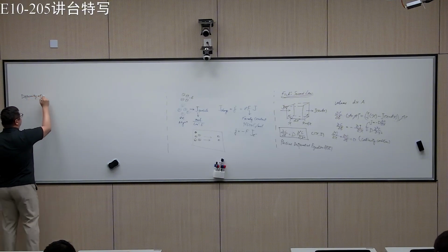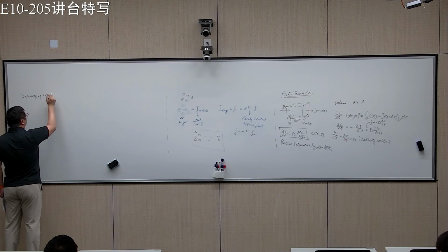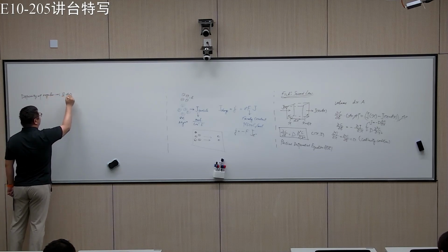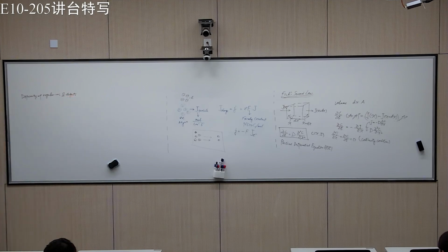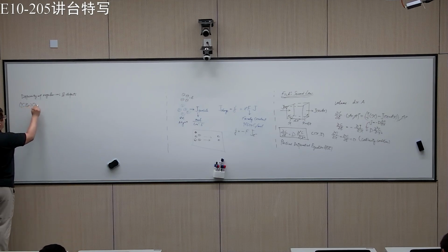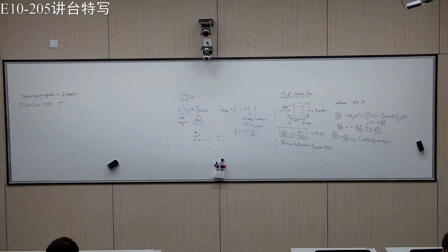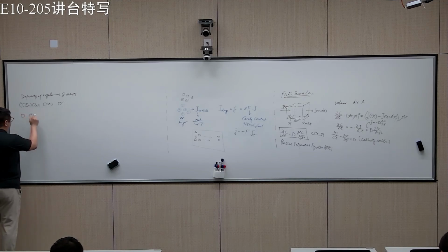of regular ions and defects. Okay, what does it mean? Let's take the yttrium stabilized zirconia as an example. Essentially, for this guy, we call YSZ, at high temperature you have oxygen ion conduction, so oxygen ions can move. However, the oxygen ions cannot actually move if you have a perfect lattice.